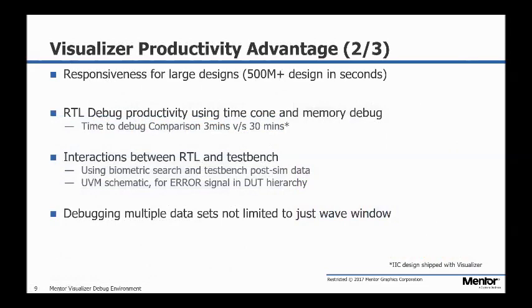And then once you are debugging on large designs, I don't know if any of you have ever been debugging in the traditional Questa debugger. When you have a really big design with a lot of wave data, you are zoomed in and you zoom out full, and it takes like 30 seconds for the waves to slowly propagate across the window. Feels like about 10 minutes when you're actually doing it. That is indicative of the fact that the traditional Tcl debugger is hitting its capacity limit, whereas that's completely instantaneous within Visualizer.